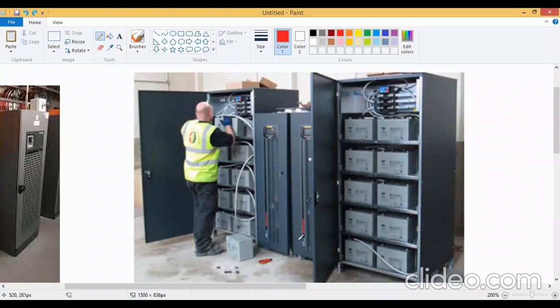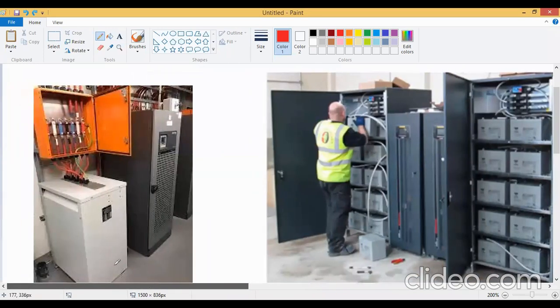You can see a box over here. This box is nothing but your actual UPS, which does the function of AC to DC and DC to AC. And obviously these high voltage, high current batteries are there. That's why large size wires are required. You can see over here, this is a UPS. There are many functions over here. You can trip the supply at one particular time if required. You can make it online UPS or offline UPS. Two modes are available in recent UPS as well.